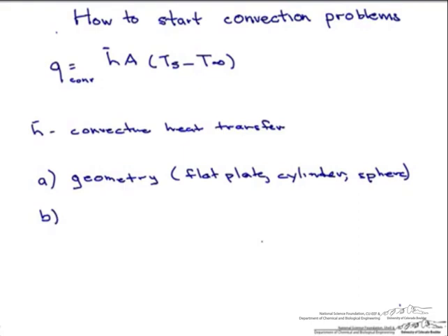Secondly, fluid properties change sometimes dramatically with temperature, so it's important to pick the correct reference temperature to look the properties of the fluid up.